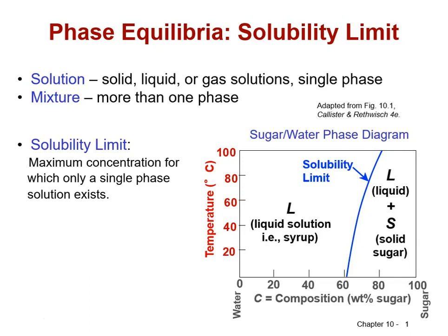You can have one or two things dissolved in another, so you could have multiple solutes in a given solvent. And the solvent in this case is usually defined as simply the majority phase. And again, you may recall having heard that from our Hume-Rothery solid solution rules back in solid solution defects and alloys earlier in the course.